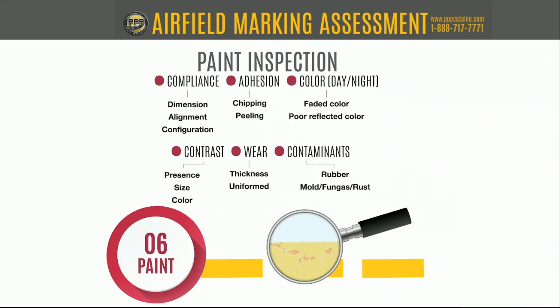Right. So as far as the paint inspection, we're really talking about looking at the stripe itself, not necessarily getting real granular into the bead embedment, distribution, things like that. We'll talk about that next. But when you're looking at the actual stripes, you're taking a look at compliance with either the FAA or perhaps Air Force, UFGS, something like that.